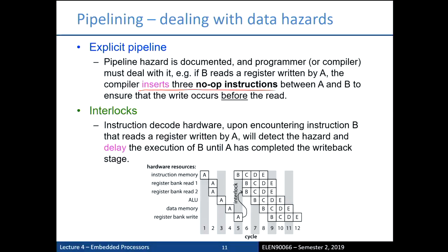So it looks very similar. So this actually looks very similar to the explicit pipeline, where these would be no operations here. But here, it's a hardware-based interlock. It locks B from running. Doesn't even fetch it. Okay, until A is finally written to the register. While it's doing that, you can be fetching B. So the next cycle, when you read B, it's already settled.